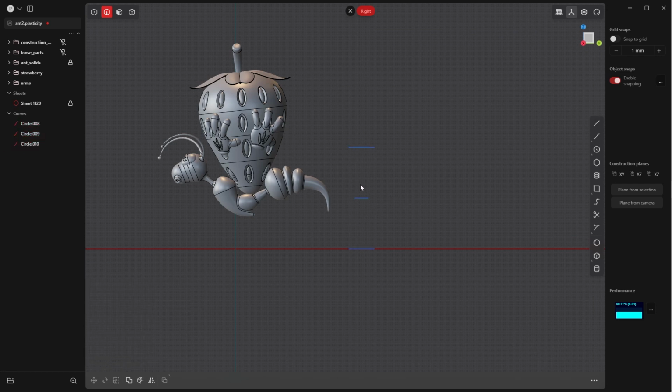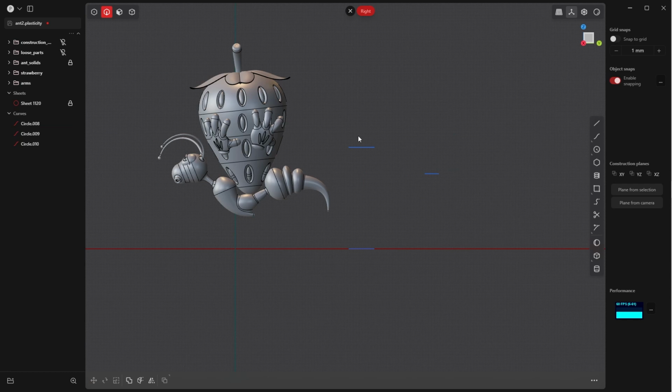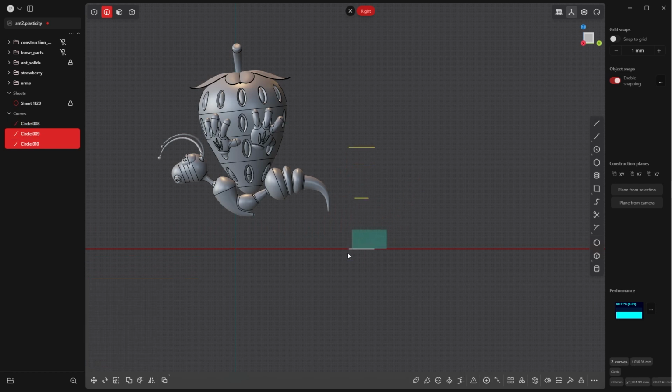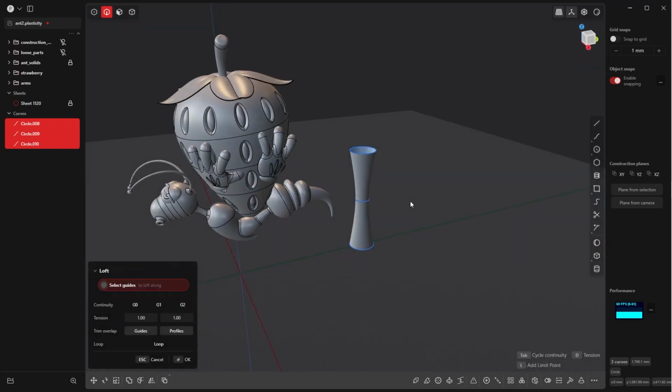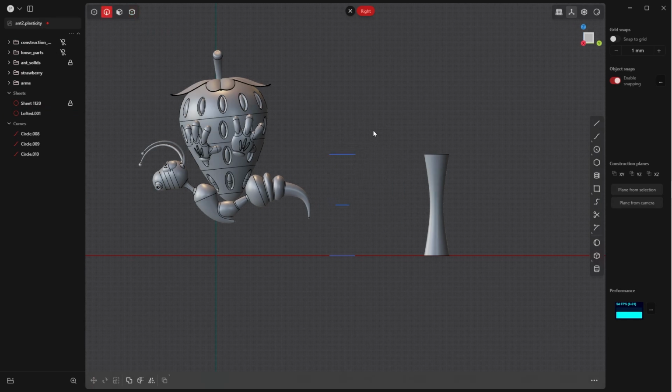And by the way, when you are lofting, select the curves you want to loft along in the correct direction. Otherwise, it may give you weird results. So if we select the curves like so and press loft, you can see that the lofting operation goes in that direction in which you have selected your curves, in the order of the curves. If you select it in the correct direction, you will get the desired result. And that's okay. We don't need these sheets any longer.